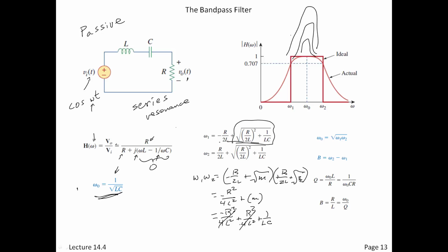And we saw that definition of bandwidth, and Q was kind of the sharpness of that peak. We could rewrite it this way, as Q is equal to the center frequency divided by the bandwidth. So the smaller the bandwidth, the higher the Q, the sharper it gets, right? We saw that earlier. These equations, these circuits, the analysis keeps coming back.